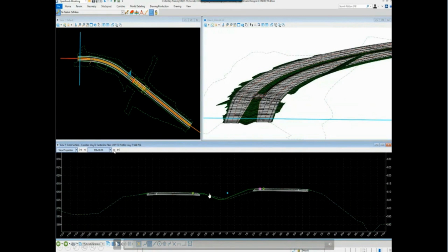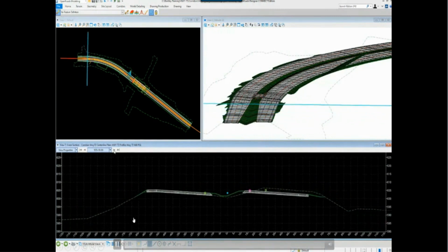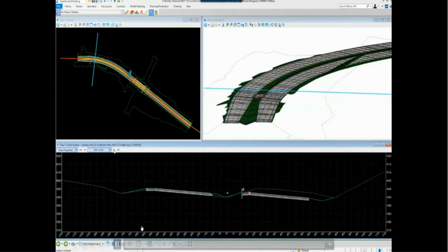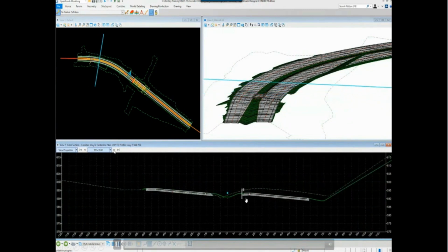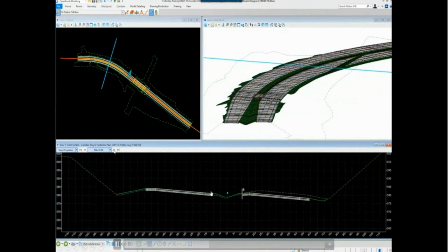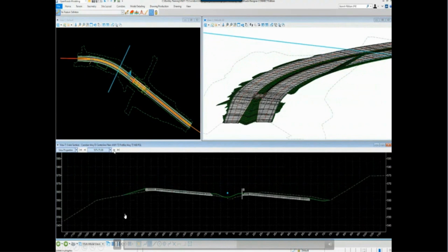We will modify, again, the eastbound lane, to meet existing both horizontally and vertically, and then we'll transition that back down to, again, our level or our even PGL. And as we walk through these sections, you can see now our elevations from westbound here and eastbound are equal at the same PGL. And so really that's our objective throughout the course of this project. Again, we're creating the geometric layout for that today.